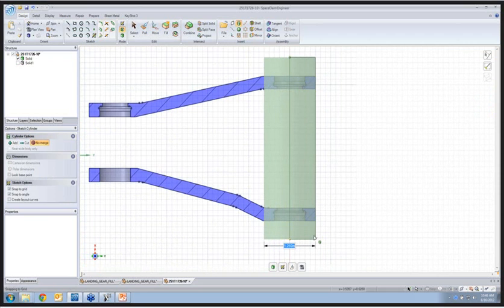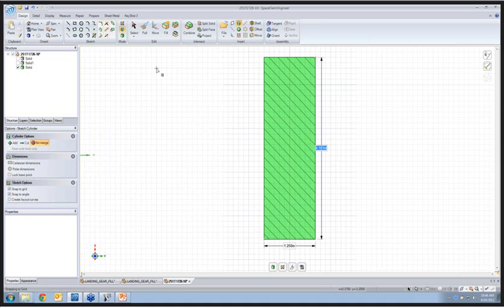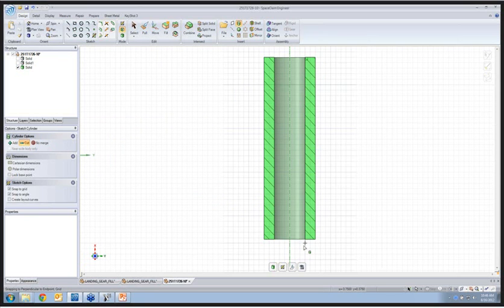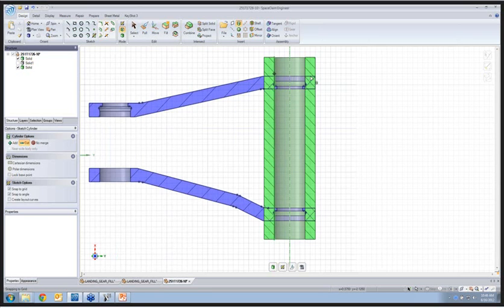I'm using, instead of a pull tool in a sketch, just a dedicated cylinder tool, which just throws a cylinder somewhere in the model. Now, I obviously don't have precision on it quite yet. I'm roughing something out that's 1 1/4 diameter, but I want to cut a hole through the center of it. After all, this is just going to be a shaft, or a tube, if you will. It'll have a through hole, 3/4 of an inch. The size of this might be something I could just buy off the shelf, okay?